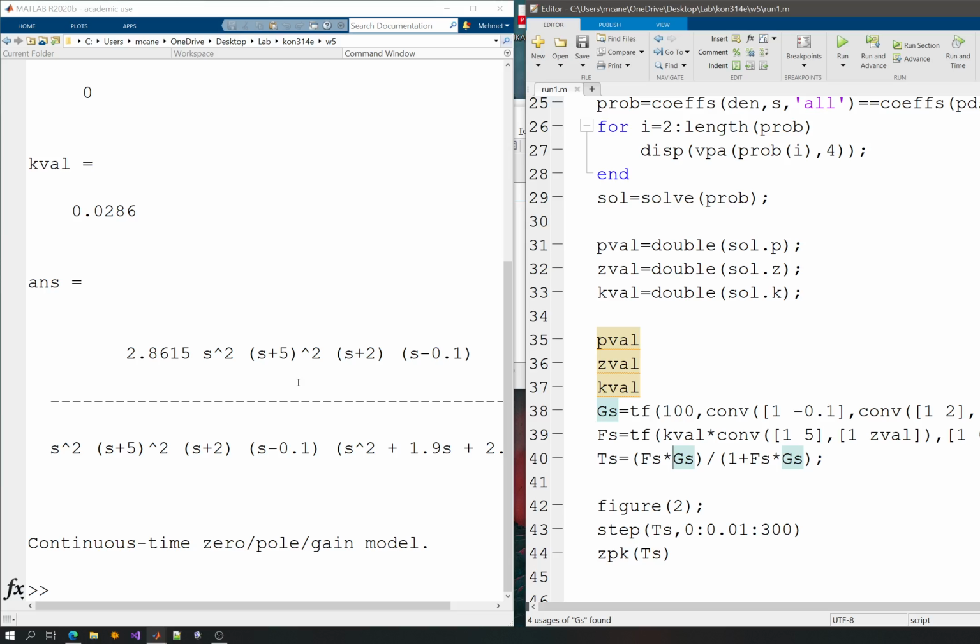If you're a little bit on the left, 0.1, 0.2, depending on the system, this effect may be not that big, but exactly at 0, you cannot guarantee that. So you shouldn't be designing this controller just for the fact that it has a zero cancellation at the marginal stability at the origin exactly. So it's not a good idea.